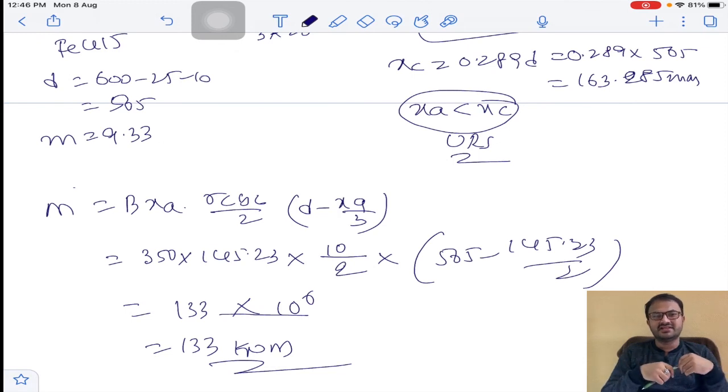But working stress method is not that important for GATE, but you need to know the difference between working stress method and limit state method. Okay, so what is the difference if we design a beam by working stress method and limit state method? Generally by working stress method we will get larger dimensions, and in the limit state method we will get smaller dimensions. When smaller dimensions are provided compared to larger dimensions, obviously there is a saving of material. As the course is related to bridges, they are explaining all this content related to working stress method.